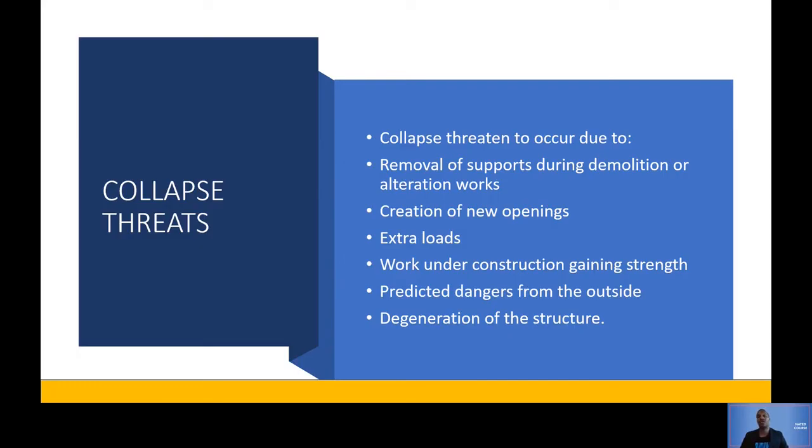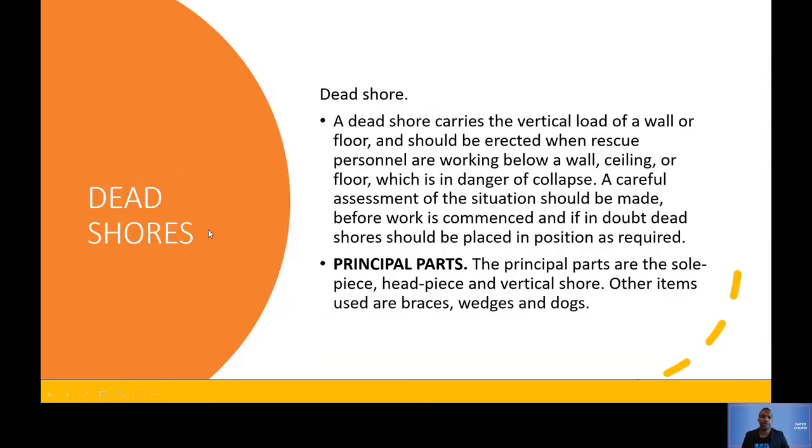Degeneration of the structure. Let's say the structure is old, so it's degenerated, it needs extra support for it to be strong again, so you put strong shoring. So these are all reasons to put shoring in.